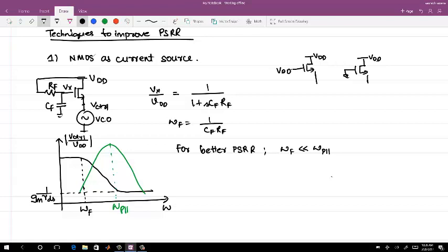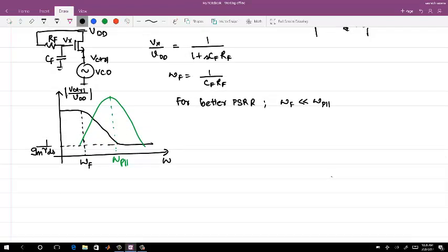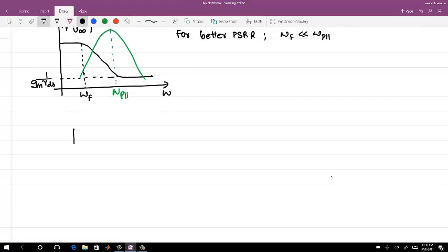If you want to think of it simply, here I am going to control VDD with whatever my loop filter output is, with some buffer which can give all the current, and that voltage is just coming as VDD. If we want to use the NMOS directly, with V control coming into an amplifier controlling this NMOS, then we can use this one. Then you need to see what happens. I'm not going to talk about this.